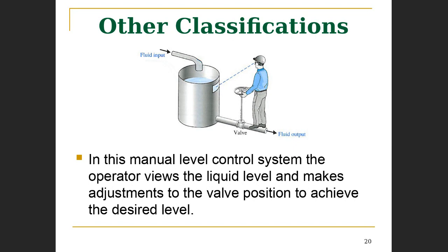I'm hoping that you can see that there's some amount of feedback, and here, this is not electronic feedback, right? So you may find that some material might say, okay, in the absence of electronic feedback, the system is open loop. But here I'm laying a foundation to say, in my definition, once you have measurement, it doesn't have to be electronic. Once you have measurement of the variable you're seeking to control, then it's a closed loop system.